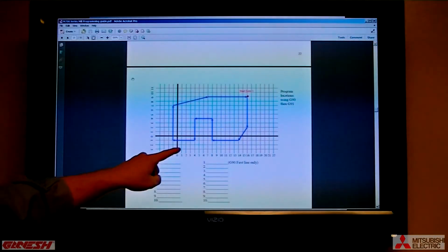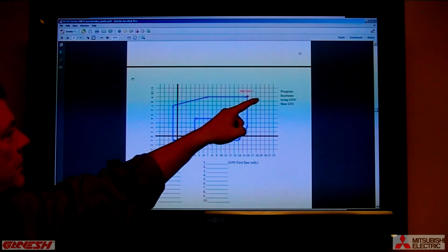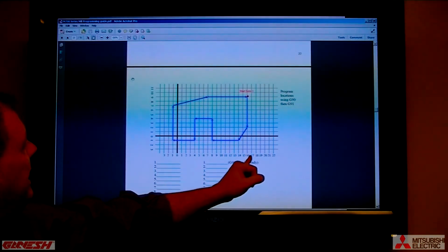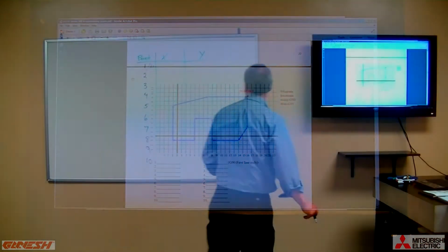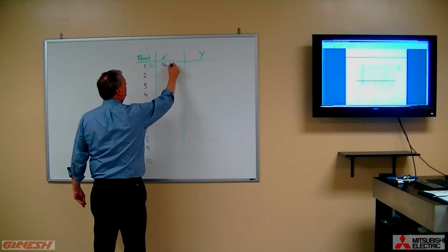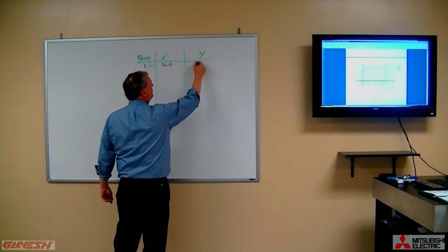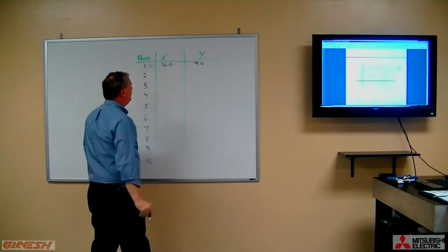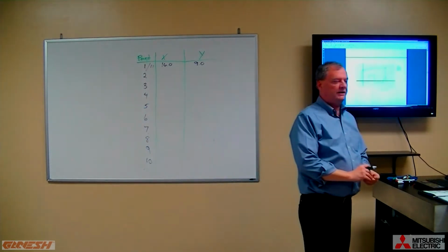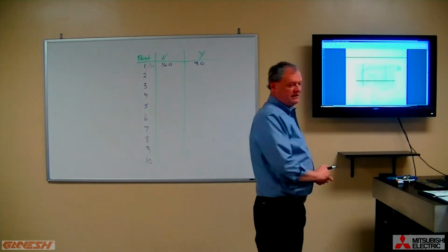So let's start by saying, okay, this is point number 1 right here. This correct answer would be a value of x16 and y9. So for point number 1, it's x16.0 and y9.0. Now I'm starting to look at putting in dots for decimal points and 0.